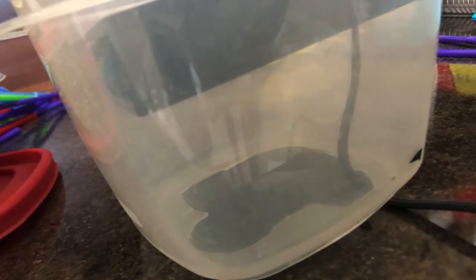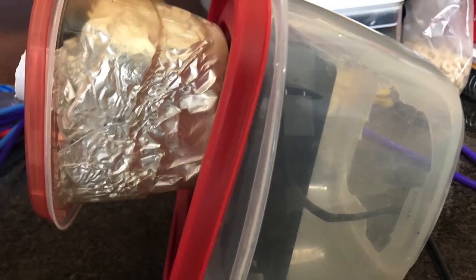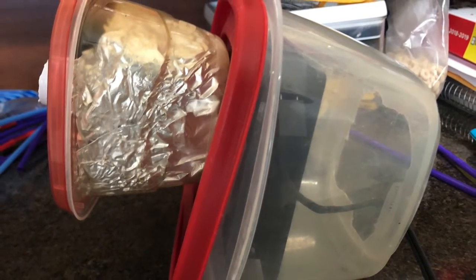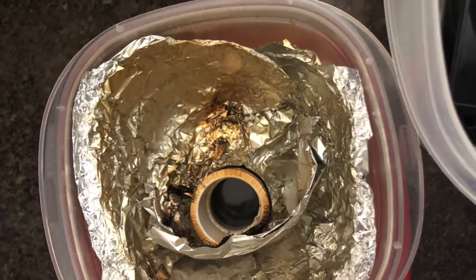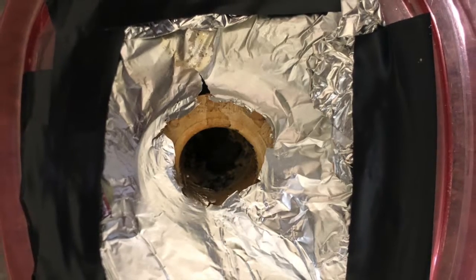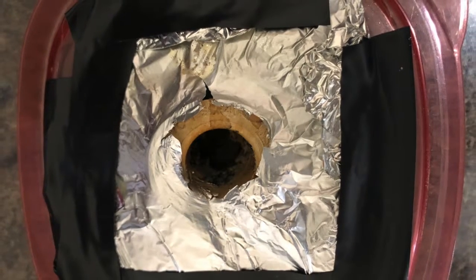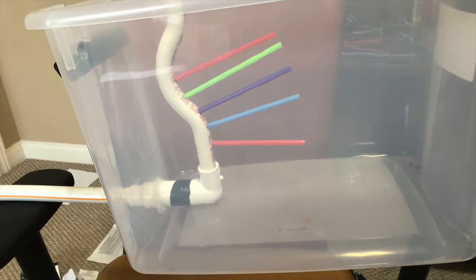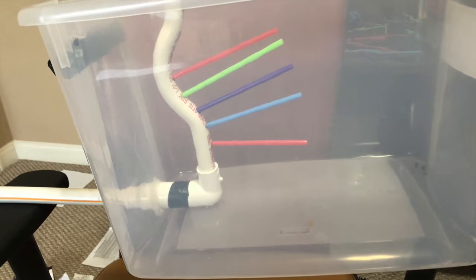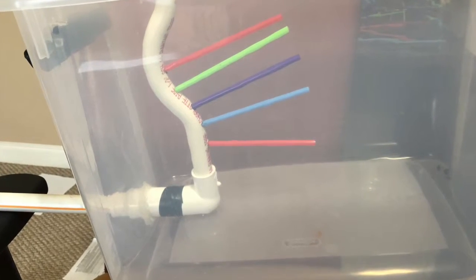The fan pushes this smoke through this long horizontal tube that has all the filters to straighten out the eddies and all the turns in the smoke. Once it's straightened out, it goes to this vertical tube that also straightens out the wind just a little bit more, just so we can get that straight wind design that we want. To get this streamline, we essentially put 5 more straws just to straighten it out even more and as much as possible, just to make sure that we don't have a turbulent flow at the end.